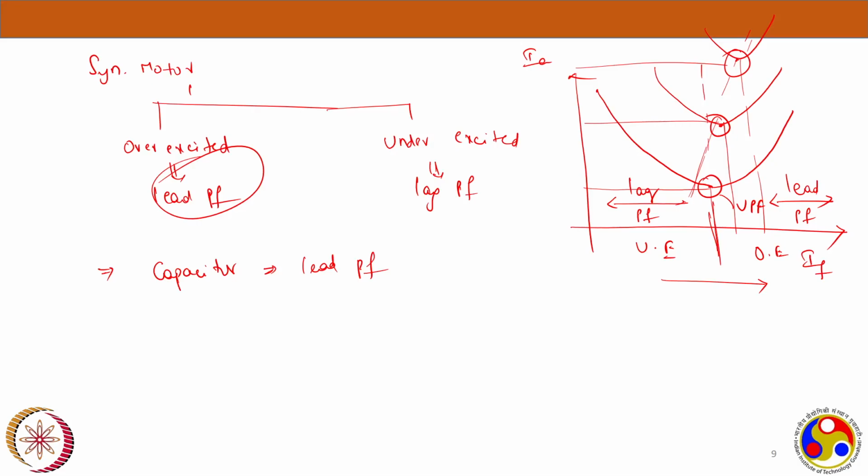So let's say you have a very big factory with all the motors and machines running all over. Now, usually, what motors do you have in a big industry or factory? Induction machines, because of their rugged construction, low maintenance and good operating power factor, 0.8, 0.7, whatever it is. So you will have induction machines all over your factory. Induction motor loads are usually lagging. Induction motors always provide a lagging power factor.